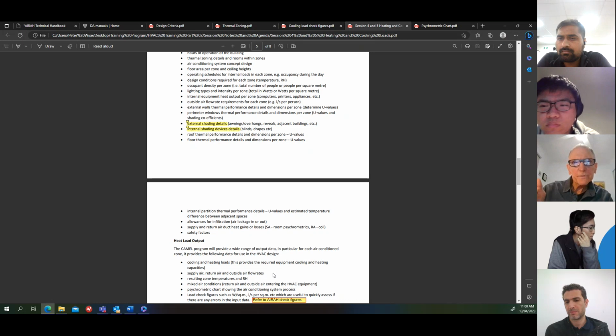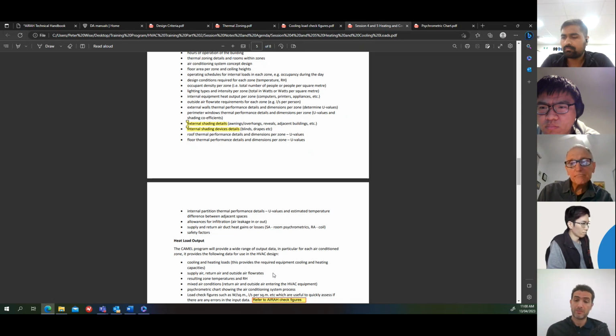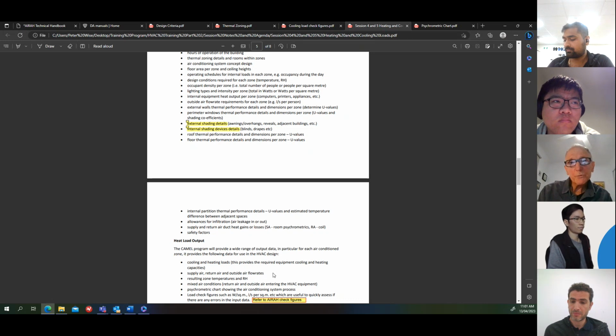But I've done hotels where we've applied a diversity factor of 50%. Wow. Which is pretty extreme, but that's how it was, because the management of the hotel said, well, look, we probably wouldn't have 50% of the population in the hotel during the day.